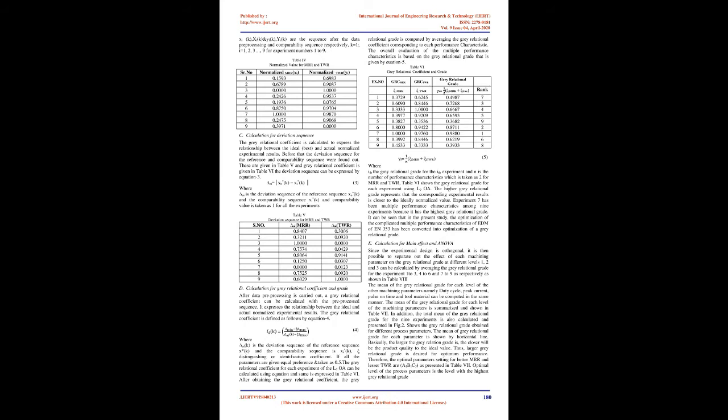B. Design of experiment. Experiments are performed randomly, according to the L9 orthogonal array generated by Minitab 17 software, on N353. For each experiment a separate electrode is used. The machining time is 10 minutes for all experiments, noted from the timer of the machine. The electrode wear rate is calculated by the weight difference of the electrodes using an automatic weighing machine with 300 g capacity and a precision of 10 milligrams. The experiments, along with the values of various parameters for evaluating TWR and MRR based on the L9 orthogonal array, are shown in Table 2.